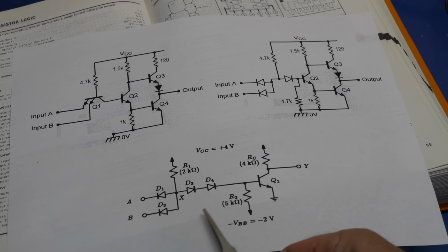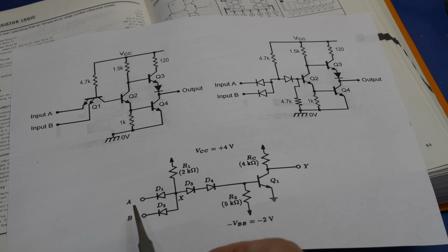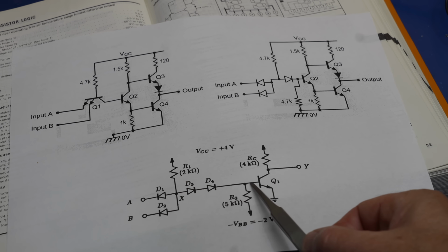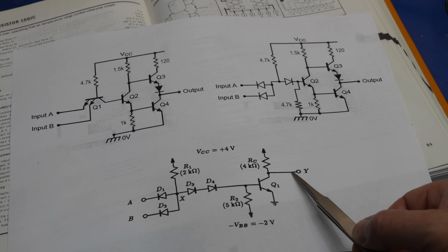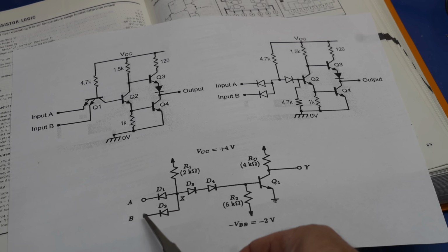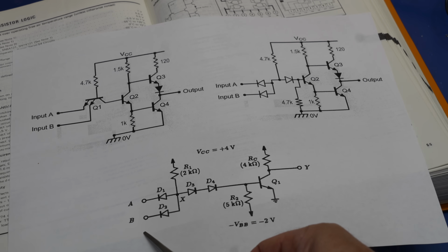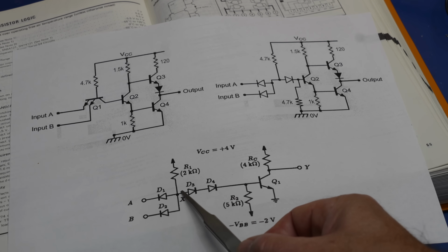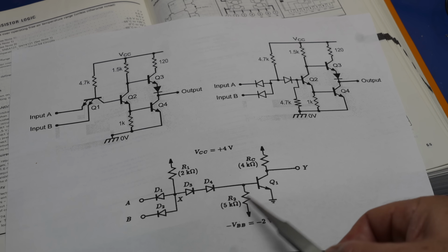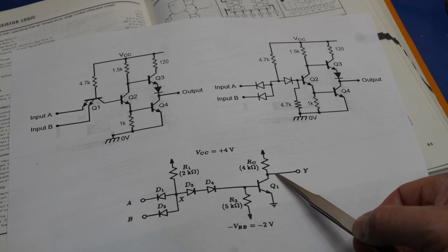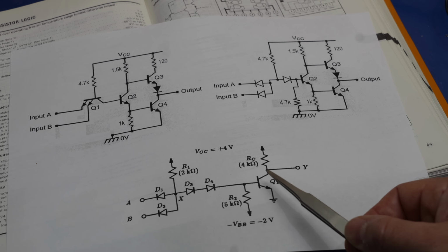So here's the original DTL gate. The way this works, if A and B are at a positive voltage, or actually not connected to anything, then the current comes through the resistor, through the diode, turns the transistor on, and this is at 0, because the transistor shorts it to ground. If either A or B or both are close to the ground, then this will be close to 0.6 volts, and this is actually through the two diode drops will become negative, and it will turn off the transistor. This comes back to 1. So this is how you implement an AND gate.